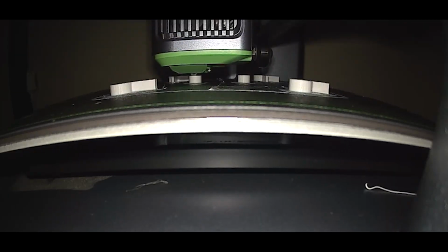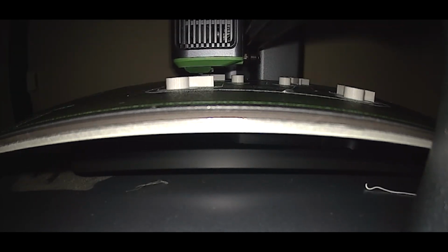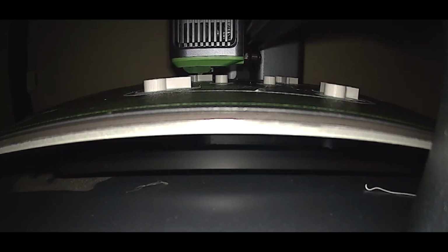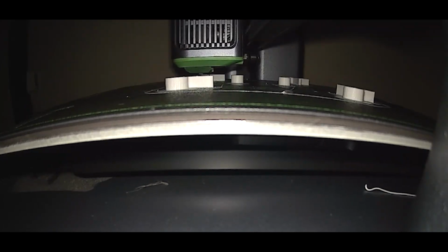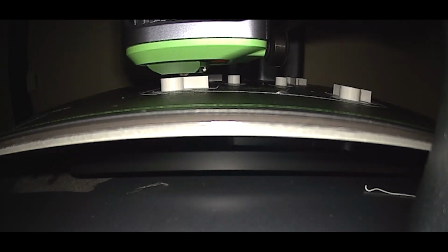Tolerances became especially important because the final system relied heavily on friction-based damping. If the clearances between the rods and guide structure were too loose, the system introduced excess vibrations and inconsistent motion during impact. But if the tolerances were too tight, friction forces increased too much and prevented smooth, controlled motion. Because of this, the rod spacing and alignment had to be very carefully adjusted throughout both the CAD development and physical prototyping.